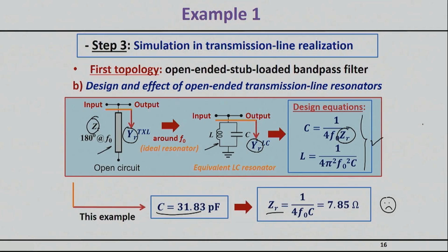If you go back to the primer on design, we have learned that for most transmission lines, you can perhaps get between 20 and 100 ohms. But if you try to implement an impedance outside of this bound, you will come into big trouble. For example, if you try to implement a transmission line that is less than 20 ohms, the transmission line will end up being so wide that it will basically start radiating. It starts becoming more of an antenna than a transmission line. And you will see this here in a minute.